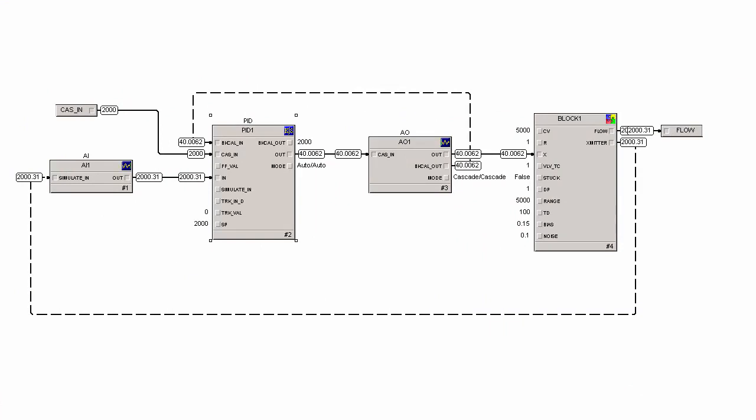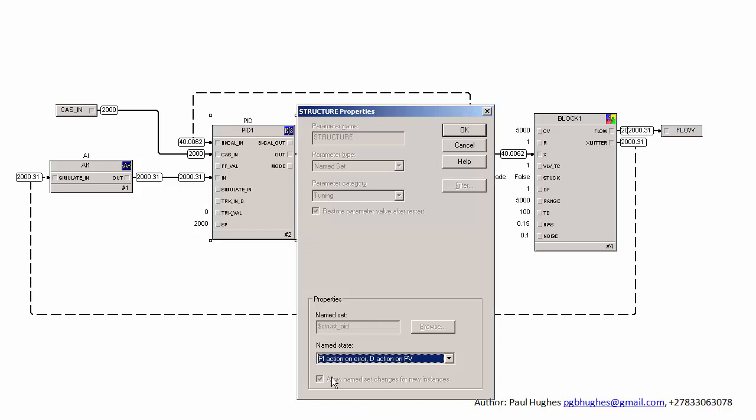So what I want to demonstrate now is just how the proportional action works for a PI-D and an I-PD. So we have this particular controller I've now detuned, so the integral effect is negligible. The controller type is PI-D.